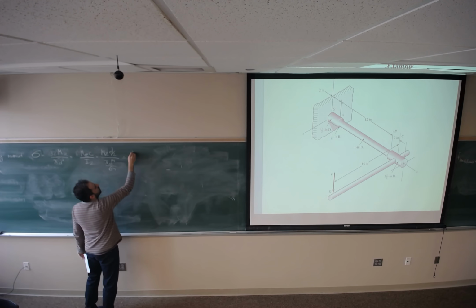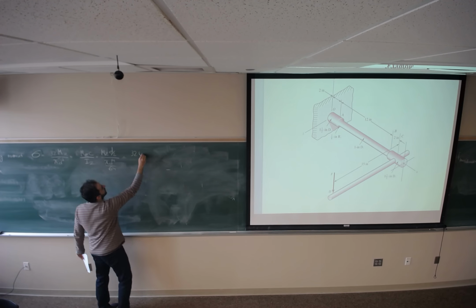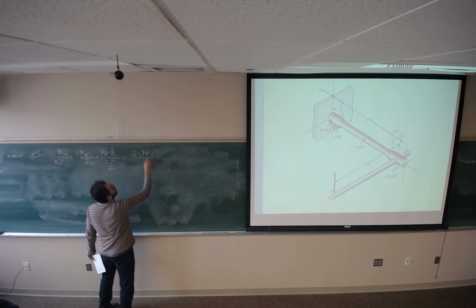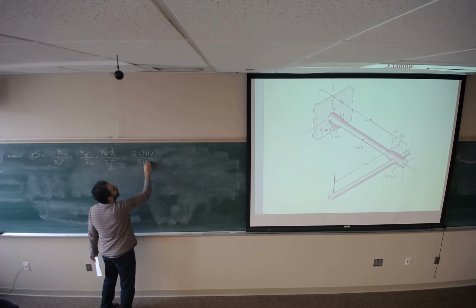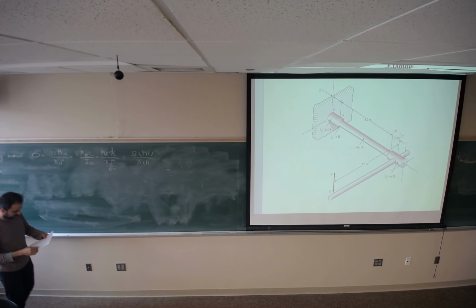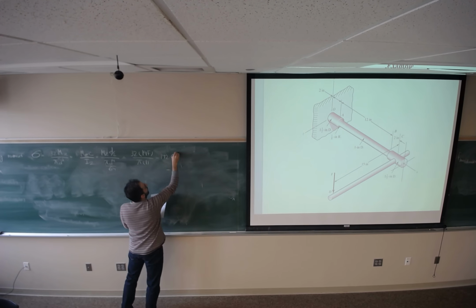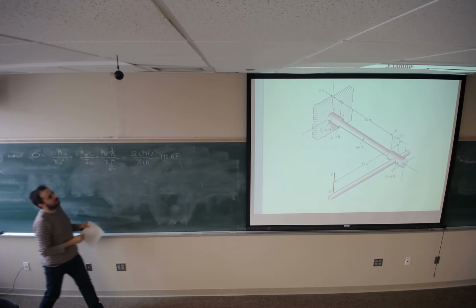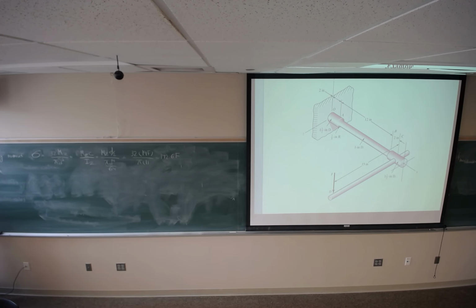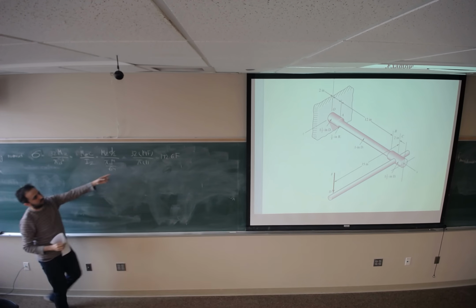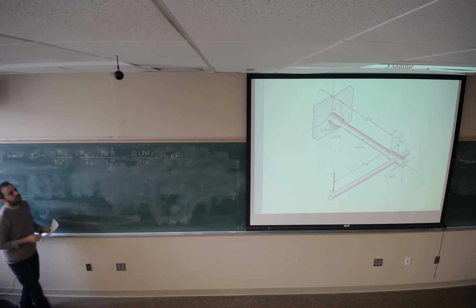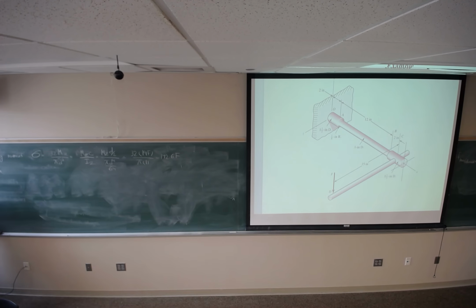So 32 times MZ, which is 14F, divided by pi times diameter, which is 1 inch. It's going to be this. I will get 142.6 F. This bending moment is making this normal stress. The goal is finding the F for the maximum allowable stress.